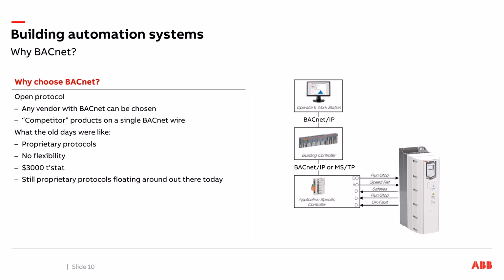So that's how it was in the old days with these proprietary protocols. There's still some floating around out there. Some of it is a little bit more in the legacy buildings, but you still see some of it in some new designs. But for the most part, if you're specifying a building, or if you're in a position to be able to make recommendations for something, definitely recommend BACnet. It is the open protocol that everybody can speak in HVAC.